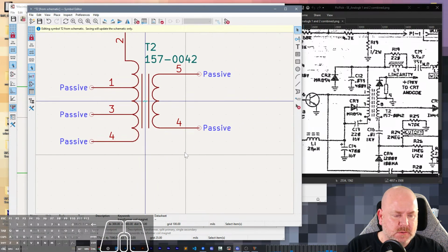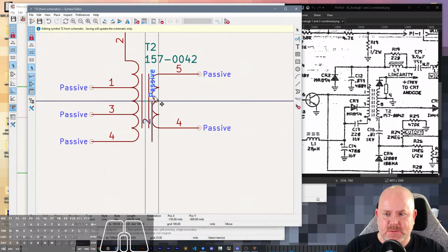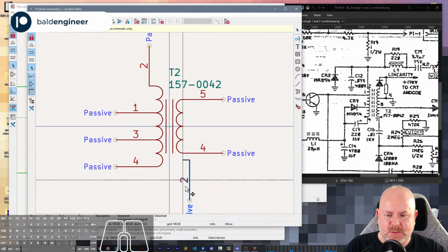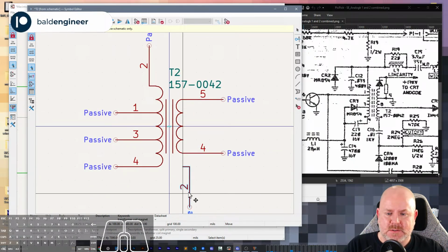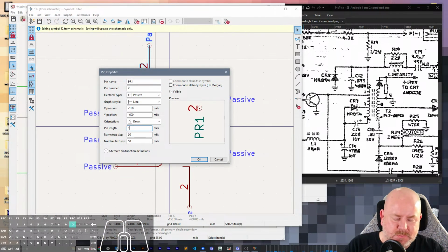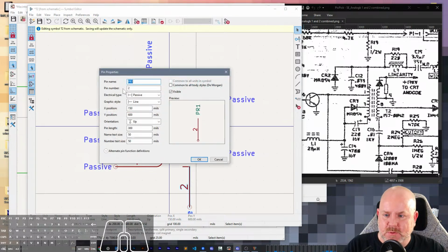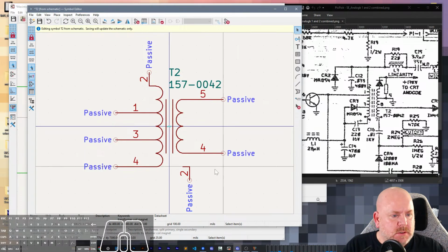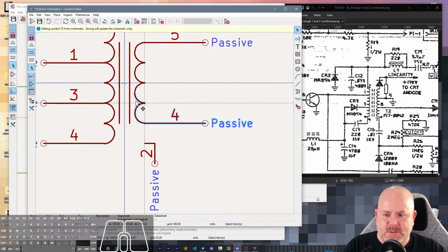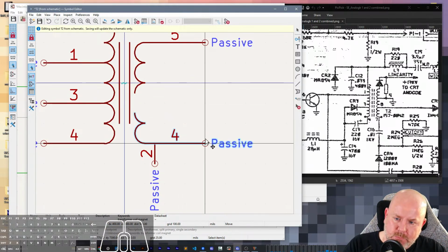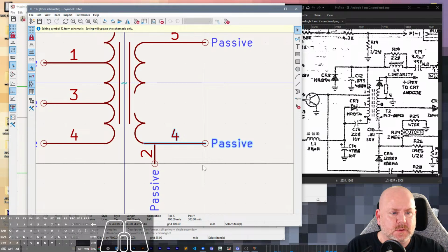And then over here, we'll bring this one. So then we got one of these. Actually, let's copy both of these things. I'm going to rotate this because we're going to say 7 right here. Oh, I was going to make this shorter because I think that's way too long. So just make it like 100 mils. We'll make this one a little bit shorter. We'll make that 100 mils. Yeah, that works. And then we can move this down. All right. Nope. There we go. That's what we're looking for.